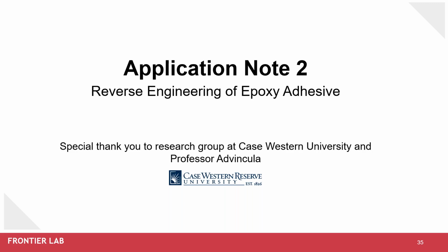And this results in a thermosetting polymer, often with favorable mechanical properties and very high thermal and chemical resistance of these samples. So epoxy has a wide range of applications, including metal coatings, electronics or electrical components such as LEDs, also used in high-tension electrical insulators, paintbrush manufacturing, fiber reinforced plastic material, and a lot more, also including structural adhesives.